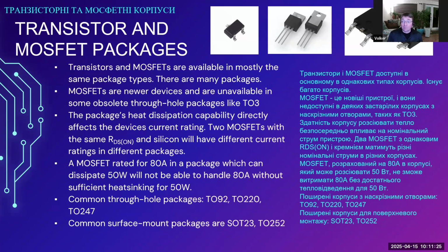The package would be able to dissipate that power, but you're not providing the heat sinking surrounding the package. So if you actually tried using that motor driver at the advertised current rating, it would basically turn into a glowing supernova because it cannot get rid of the waste heat. So that is something to pay attention to.